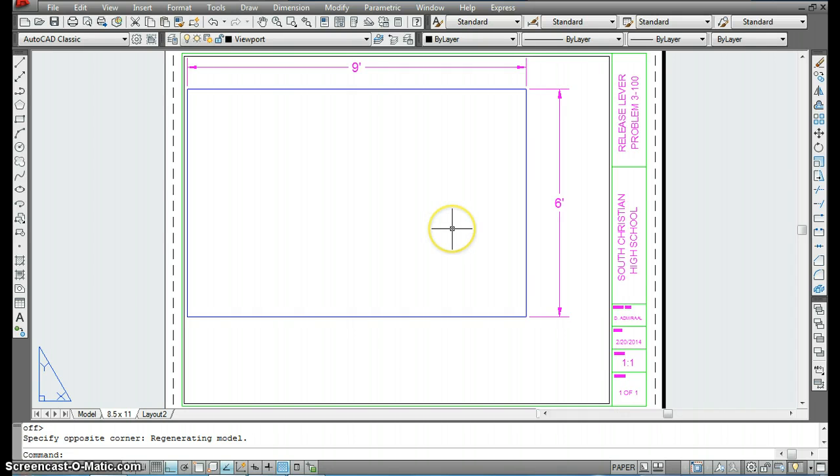You'll notice what happens is I end up with my drawing inside of this viewport. Didn't center very well, but it put the drawing inside the viewport. Basically it'll max out the size of your window and include the entire drawing there, scale it automatically for you, but typically not to a scale that we want to use when we actually plot this.